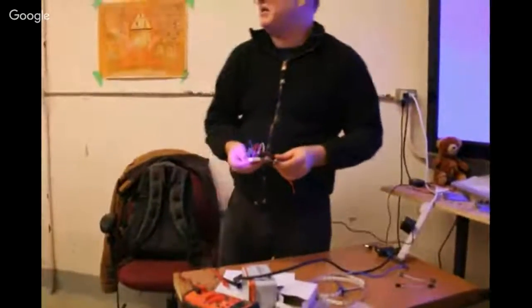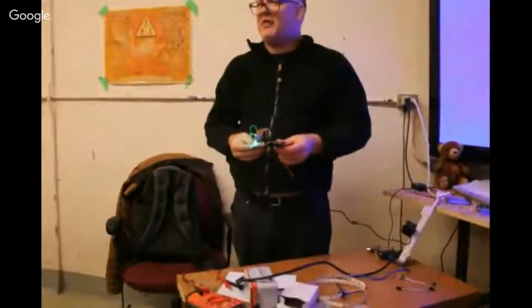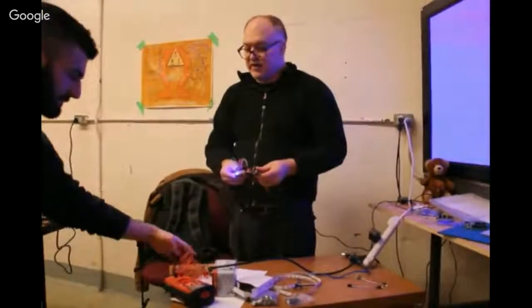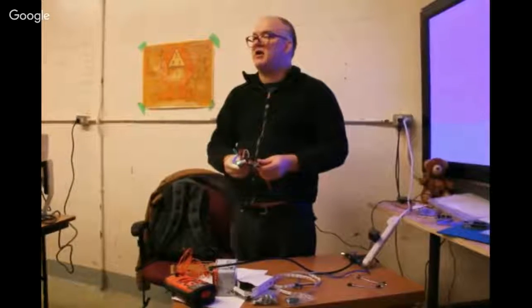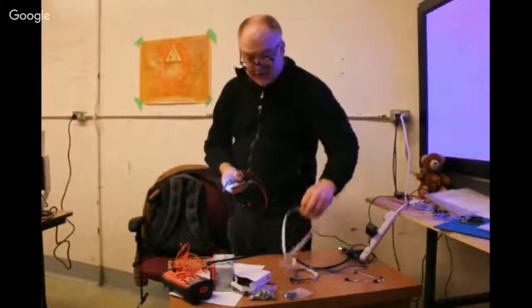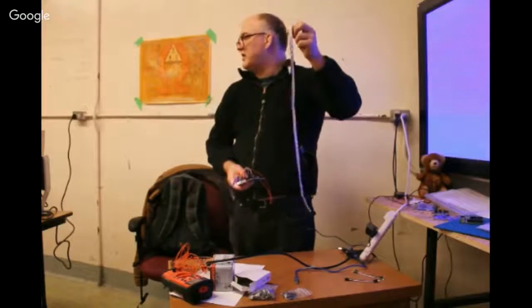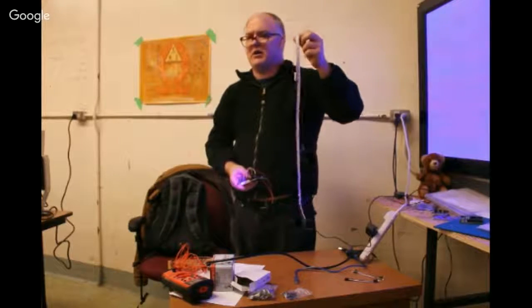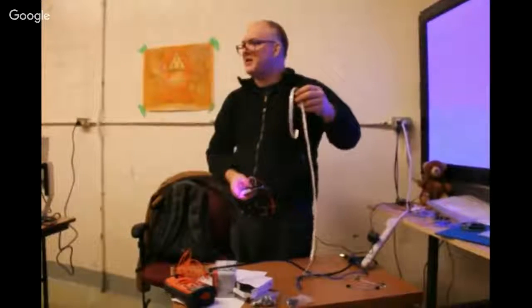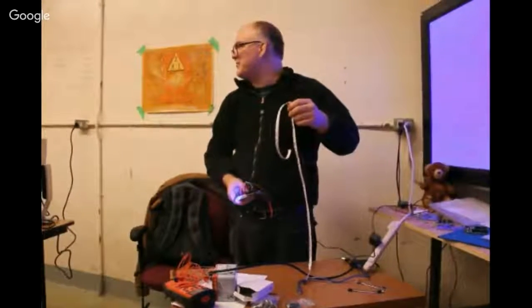So the next part of the discussion tonight is I've taken the LED strip that you'll have in your kits and have wired it up, but the LEDs have to run off of 12 volts, and the Arduino only pumps out 5 volts. The other thing is that if you use the full meter of your LED strip, you draw about an amp of current, and your Arduino pins can put out, I'll have to look this up again, but it's definitely in some number of milliamps range. You can't pull an amp of power out of any of the Arduino pins.